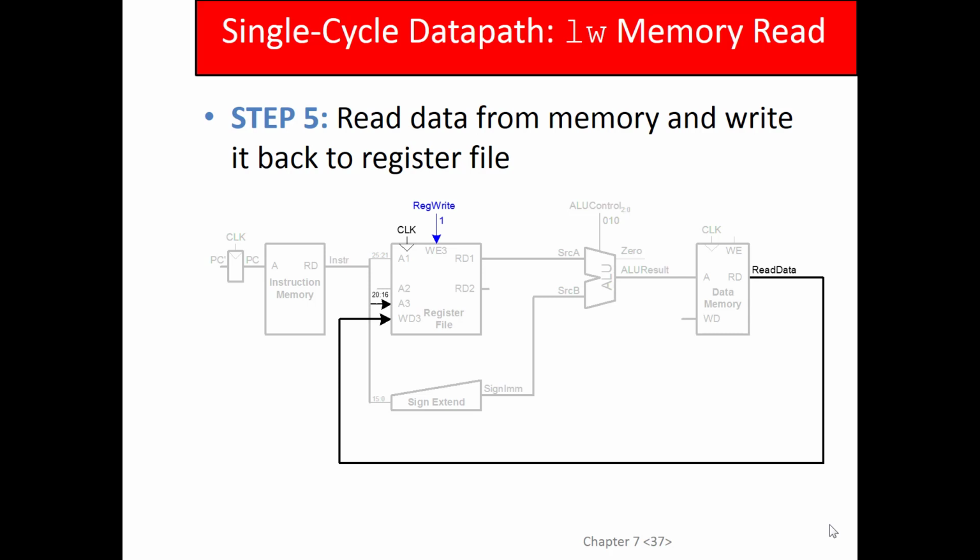I could think of an instruction register getting the instruction from the instruction memory at the address of PC, right? And then ALU A, which is that first input on the ALU, gets the reg file of IR bits 25 down to 21.